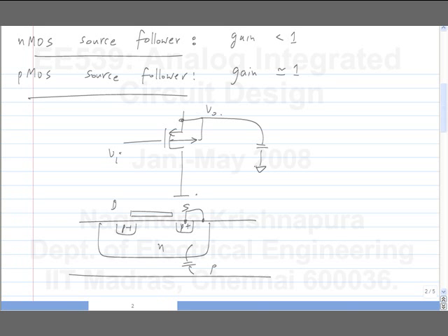There are two problems with higher frequencies. First of all, PMOS has lesser mobility, and secondly, if you connect the source to bulk, it will give you better DC performance, but it increases the load capacitance. No, it will not affect the DC incremental picture. It will very much affect the AC incremental picture, right?